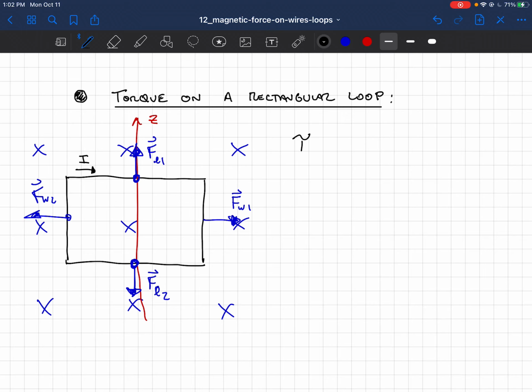So let me just remind you a little bit about the torque. The torque is a vector. It's equal to the position vector with respect to the axis crossed together with the force. So what's an example of that? You might remember something like this. You have a bar that's holding on to a sign, and you might wonder what is the torque of the force of the sign pulling on the bar. So I guess that's a tension force. So what is the torque associated to the tension force about this axis at the end of the bar?